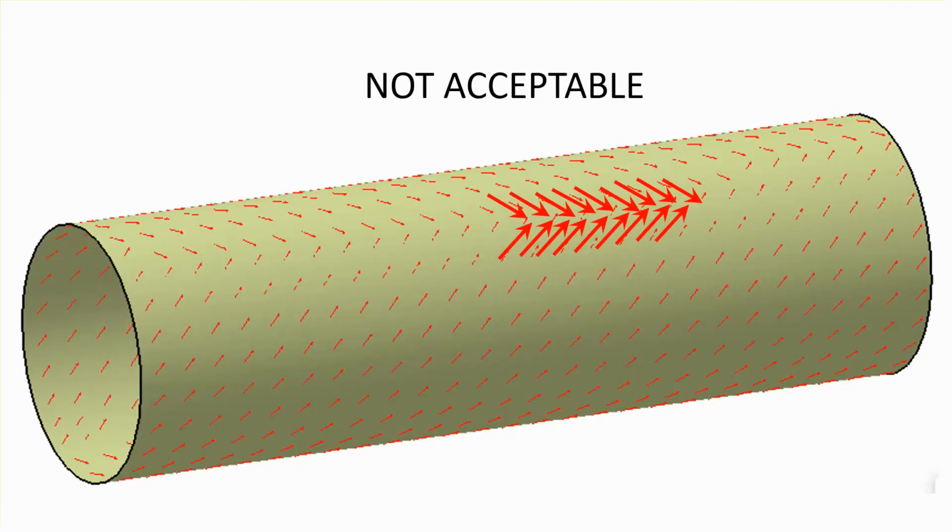Okay. Now, the reason you're going to have a hard time with a single surface is that you will notice that for a particular lamina, which is supposed to be 45 degrees, although it's saying it's 45 degrees, there's a seam here, where suddenly this angle changes.